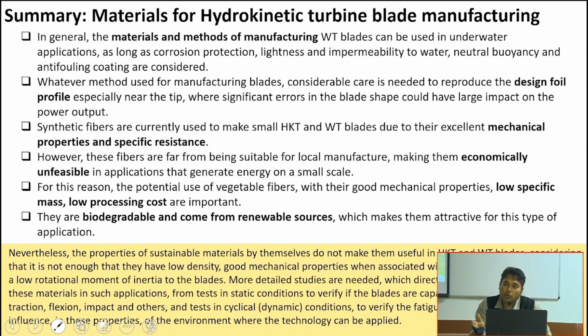Again, the corrosive property is also present in the case of the wind turbine, and that same problem will also be present in the hydro turbine. But in the hydro turbine it will be higher, and in the wind turbine it will be lesser. So from a corrosion point of view, you have to be more concerned about the material for the hydro turbine than for the wind turbine. There are different factors, and considering the properties of the material, ultimately you have to select the material which will be suitable for your turbine.